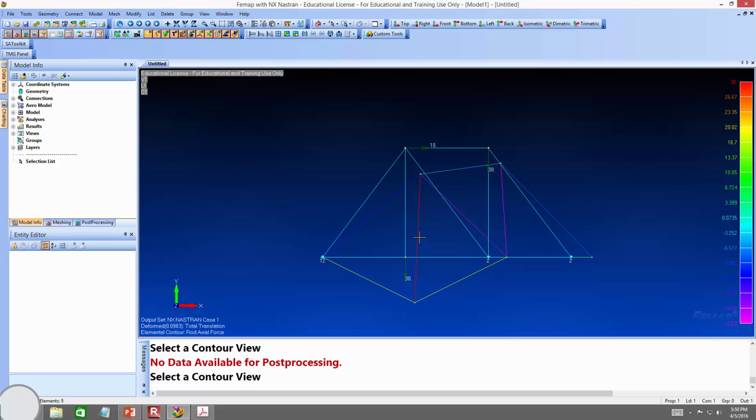All right. Now, you all are engineers. Does that value make any sense? Let's ask. Positive 30. What does that positive mean? Tension. Does it make sense that this member is experiencing 30 kips in tension? Let's go back to statics or structural analysis. Look at this and look at a method of joints analysis right here. Think about method of joints.